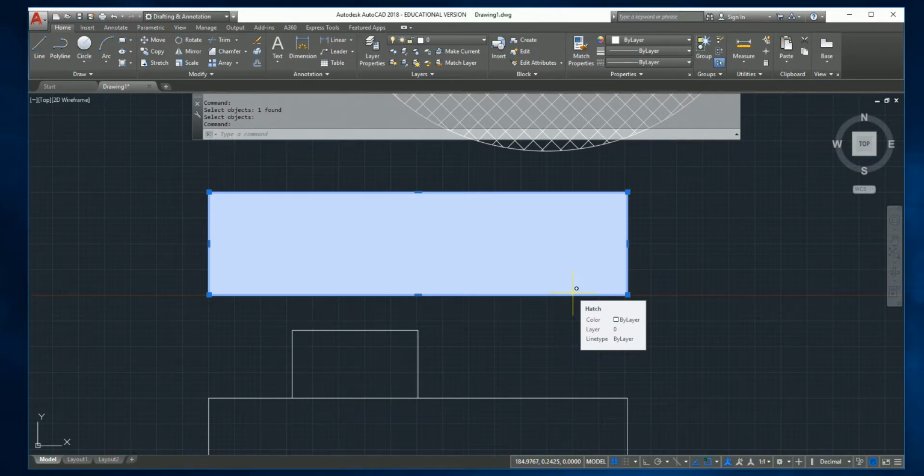So you might run into that, especially when you're drawing your plan. You want to adjust a wall or something, then you can't get it. So you may want to send the hatch to the back. Sometimes you want to bring dimension lines to the front, just so they're on top of everything, so that when you have a background mask on it, it actually works, so you don't have a line going through the dimensions, and you can actually read them.